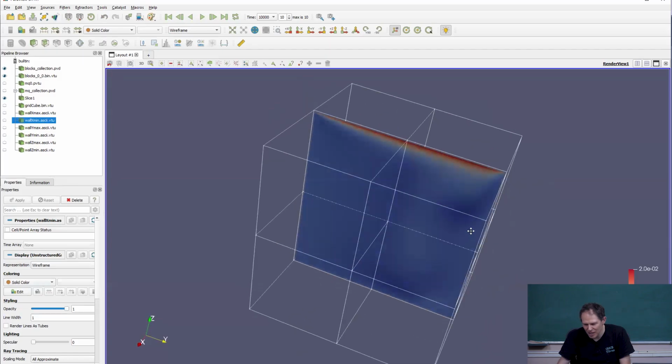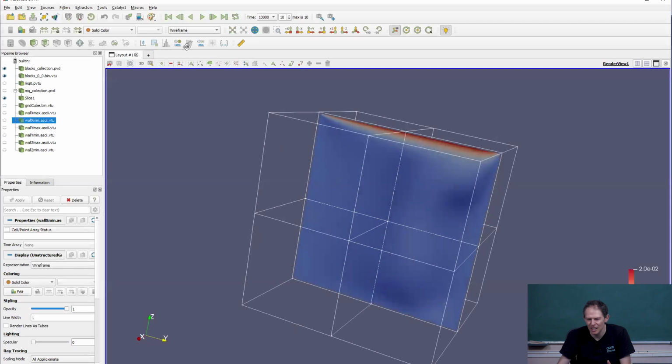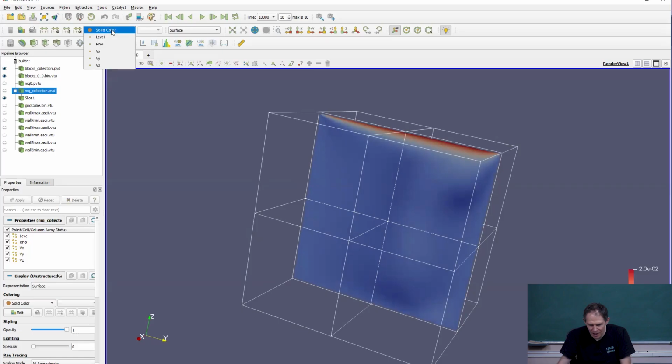Now I don't know whether you are familiar with ParaView. This is also used by OpenFOAM, for example, or you use it together with OpenFOAM. So you write out your data here, and what we usually write out is the density and the 3 components of velocity.